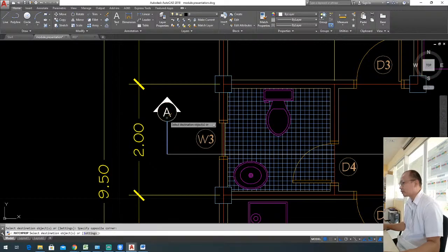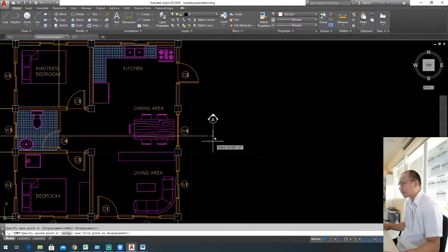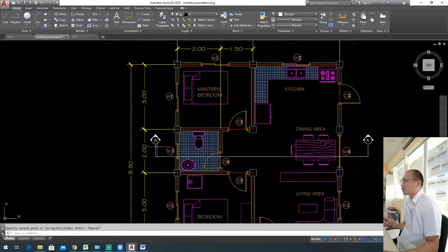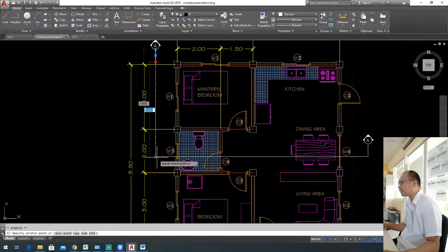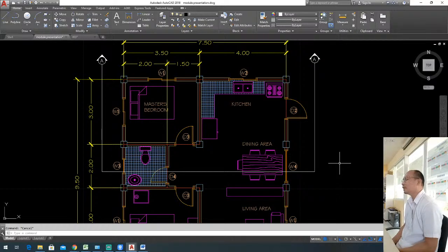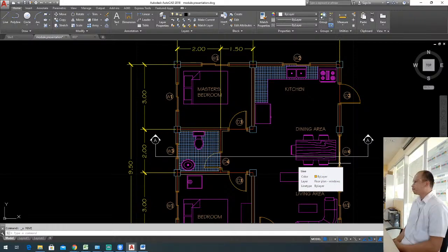Okay, first things first, because we have another line weight for that one. Okay, now copy and bring it on the other side. Now the thing here is the usual mistake on adding cutting plane line is that their cutting plane line really extended on this portion here. I don't know why. You have to extend that cutting plane line all the way here. I am not very sure why you're doing that. So you may just have the cutting plane line as much as this one.